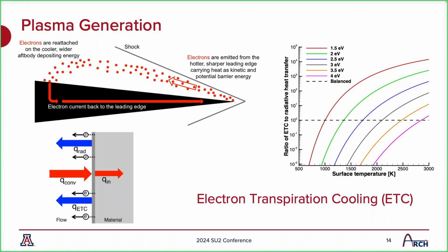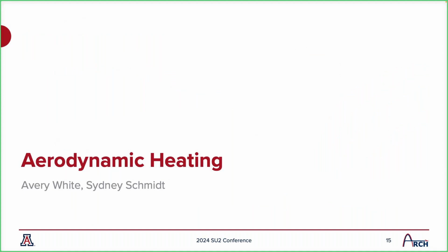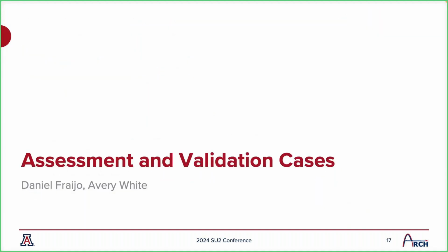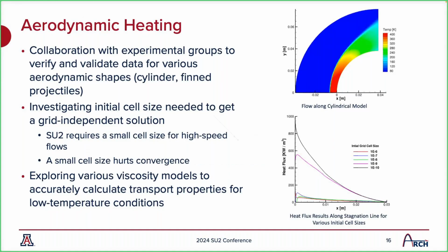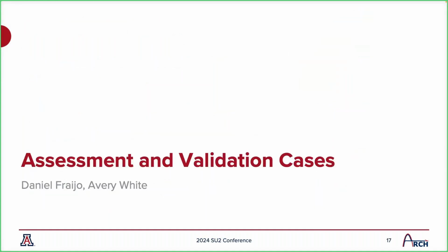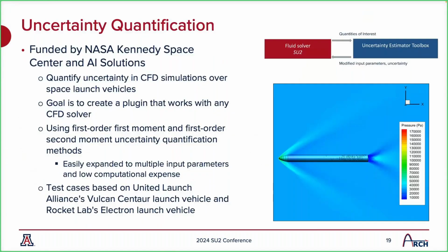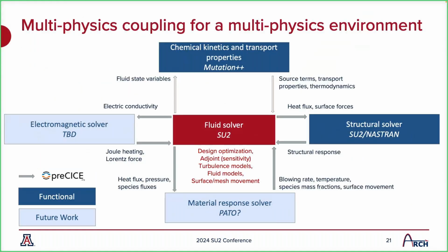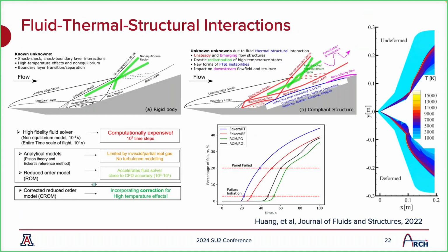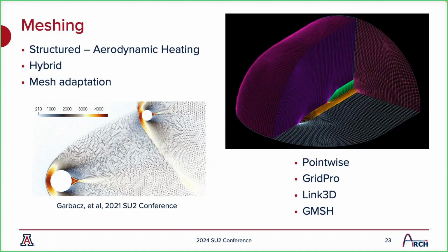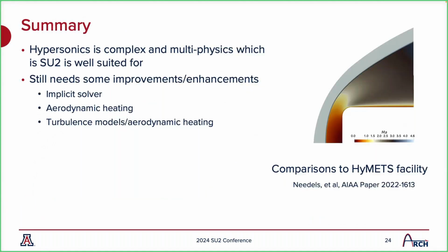Okay, thanks, Kyle. Other questions? I have one, if you don't mind. You highlighted that grid spacing is an issue. Are implicit methods what you're going to aim to use to get around that issue, or is there something else fundamental you can do? Are you just basing it on the spacing you need to capture heat flux at the wall, for example? To get an accurate prediction of heat flux, it requires a very fine cell spacing, so I don't think the implicit solver will help with that.